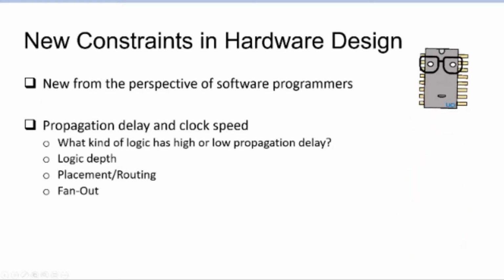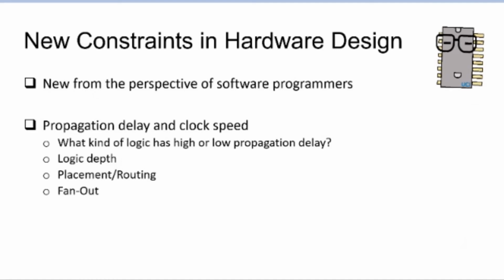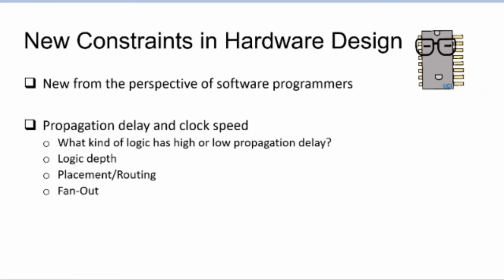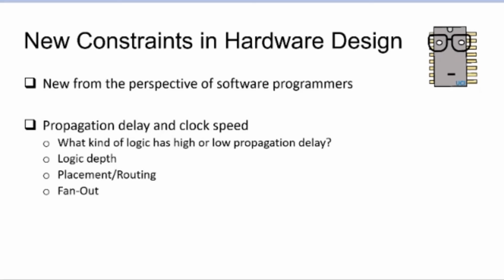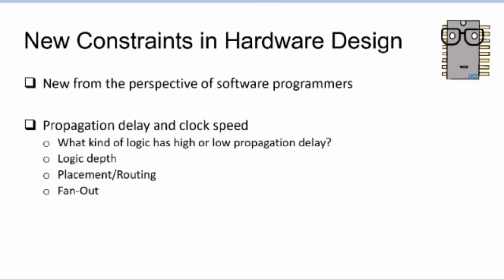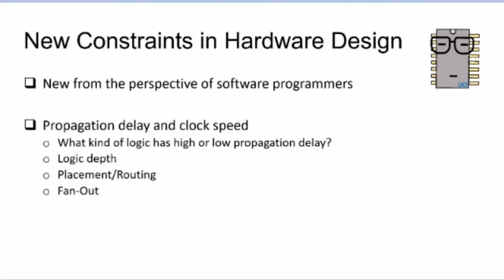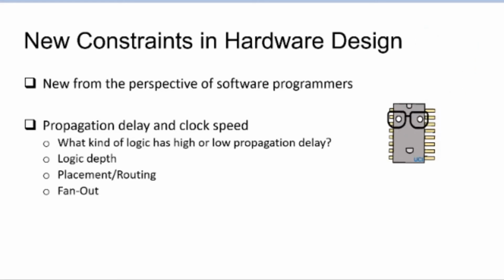The pipeline design issues that we just talked about a couple of slides ago are one hurdle that people coming from the software design aspect have to first acclimate themselves to. That's part one. Part two, another thing that software designers have difficulty acclimating themselves to when they come into FPGA design is the issue of timing.